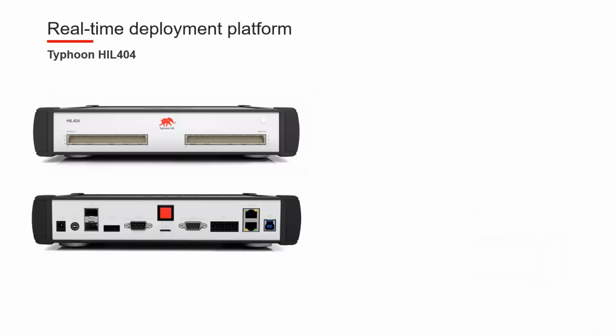So first, just a few words about the real-time platform or the real-time simulator. So it's going to be a HIL404. It's a fourth generation Typhoon's device. It's an FPGA-based simulator. It's got a very powerful FPGA board inside, which allows it to reach low simulation time steps. And in addition to that, the digital inputs that control the switches in the simulation are sampled every 3.5 nanoseconds, and this allows us to reach high switching frequency.